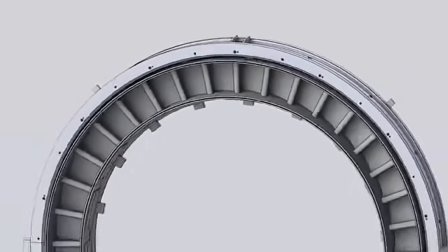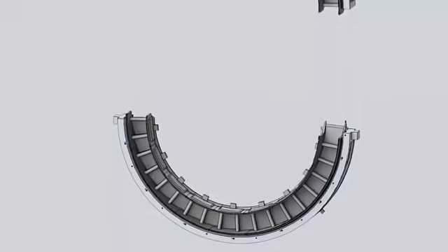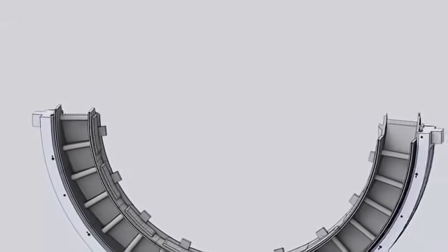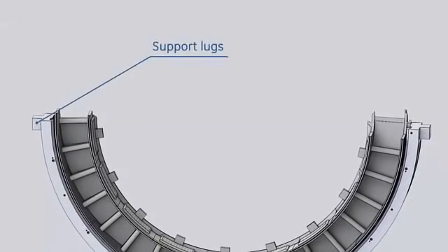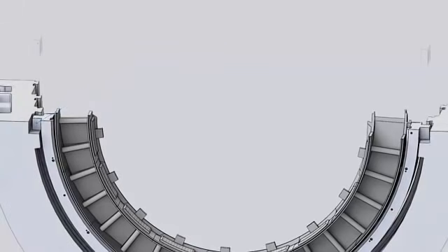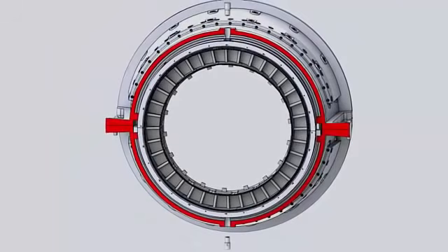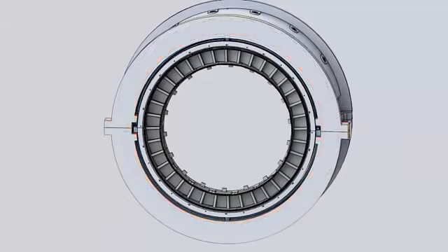The 18 segments are contained on a horizontally split retaining ring. The retaining ring is supported to the lower turbine shell by 2 lugs extruding from the lower retaining ring half and held in place by clamps. The retaining ring is centered by 2 eccentric pins from the turbine shell. This configuration permits radial expansion due to the high temperatures encountered, while the ring remains centered to the shell.